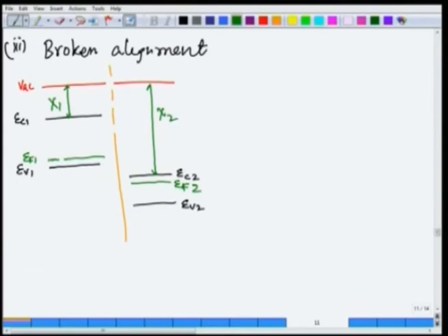What happens if you join them again? Remember, the way to do it is, imagine the material on the right, you lift it up so that the Fermi energy becomes equal. Draw the Fermi energy, draw the junction. Always draw the left material completely. So here it is, and we will just stay away from the interface. Far away, the material does not change, it remains as is, and I am drawing the vacuum level also right here. Here is the vacuum level, this was psi 1.